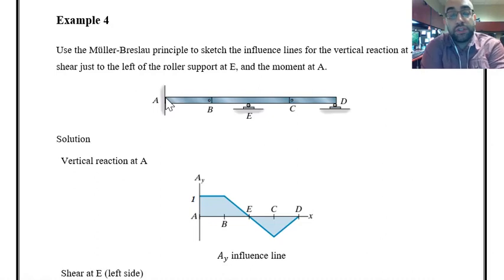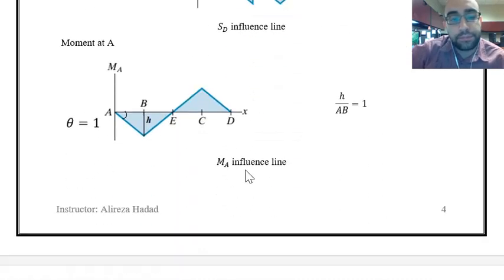The displacement restriction should be there. I cannot have displacement over there. I have to just apply a unit rotation. Once you do that, we can have something like this. Because of these hinges, we can have rotations at the locations of the hinges, and we have to make sure the deflected shape returns to the original shape or to the original location at the place of these supports. That's why we have a shape over here.